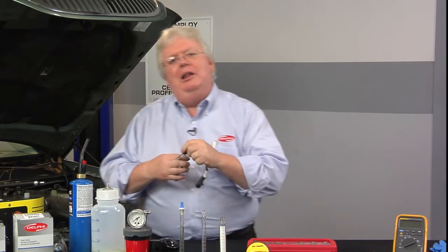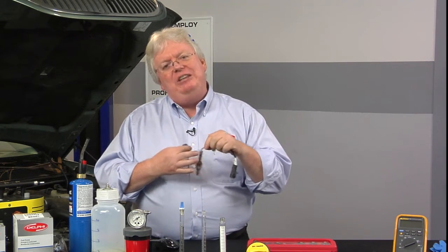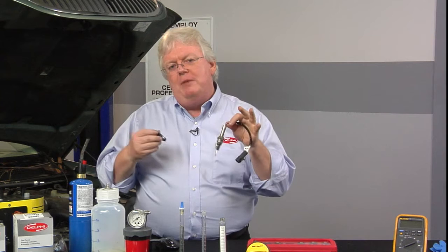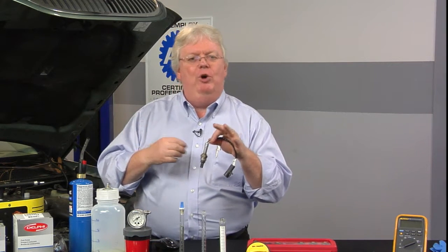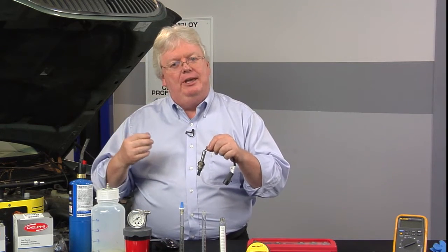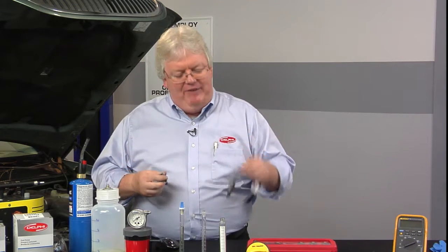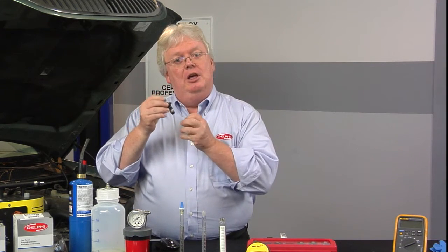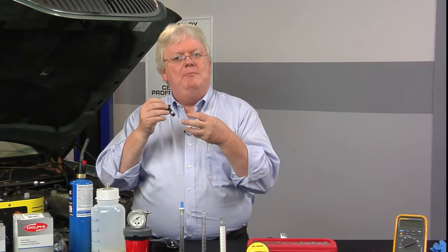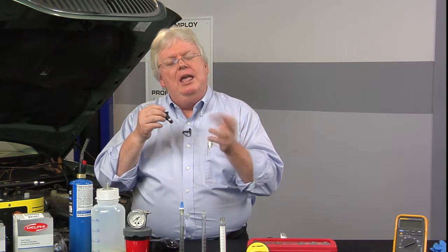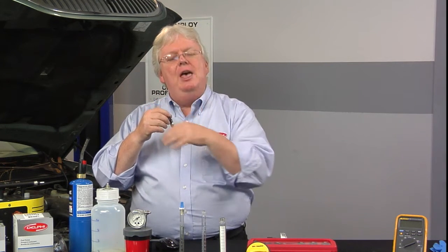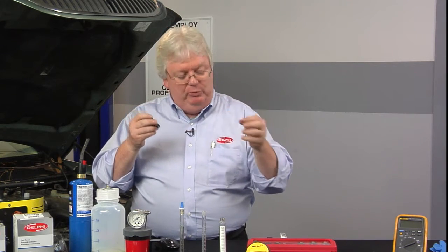But here's a little lesser known fact. When you have ignition-related misfires, the positive fuel trim increase will happen, but it won't be profound. It won't be 25, 35%. Typically it might be 10, 12, 15%. If you have an injector that's not spraying, causing the same lean mixture, the same abundance of oxygen left over, that will have a very profound effect, 20, 25, 30% positive fuel trim. They're both lean, they both drove fuel trim.